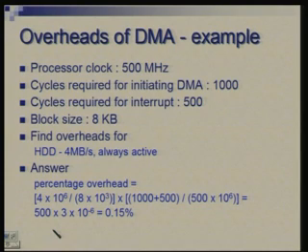So, as we have seen, from polled transfer to interrupt transfer to DMA transfer, depending upon the requirement of the device, we can choose a suitable mechanism for transfer, and as you go along this progression, there is higher and higher performance, but there is a cost issue also. DMA controller means additional cost. Similarly, interrupt also requires certain mechanism. So, there is extra hardware which also adds to the cost.